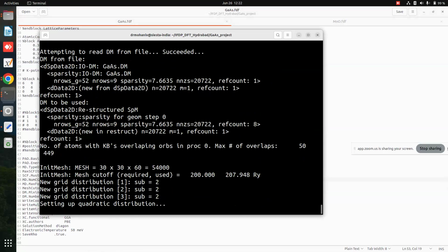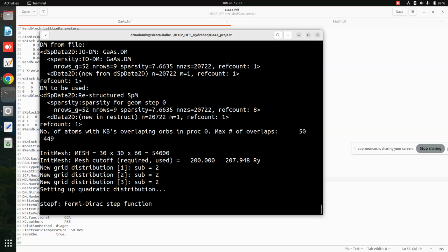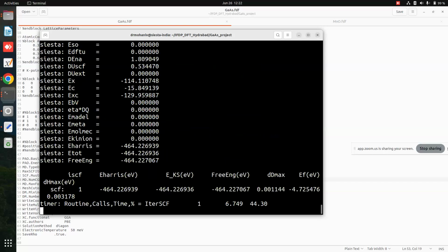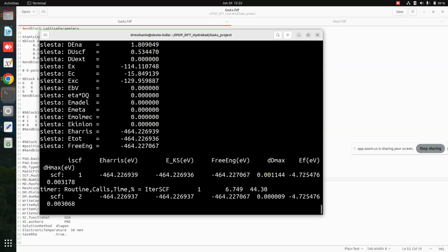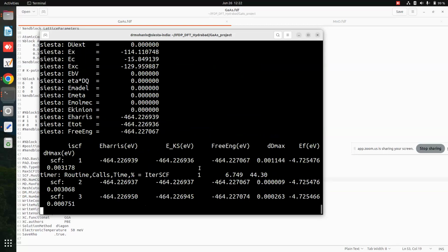In 22.04, that old command with only NP is not working. So if you want to use all the processors, then you have to use that oversubscribe term here with a single or double slash, and then definitely this will run faster when compared to the series one. So I'm giving both commands for the series.